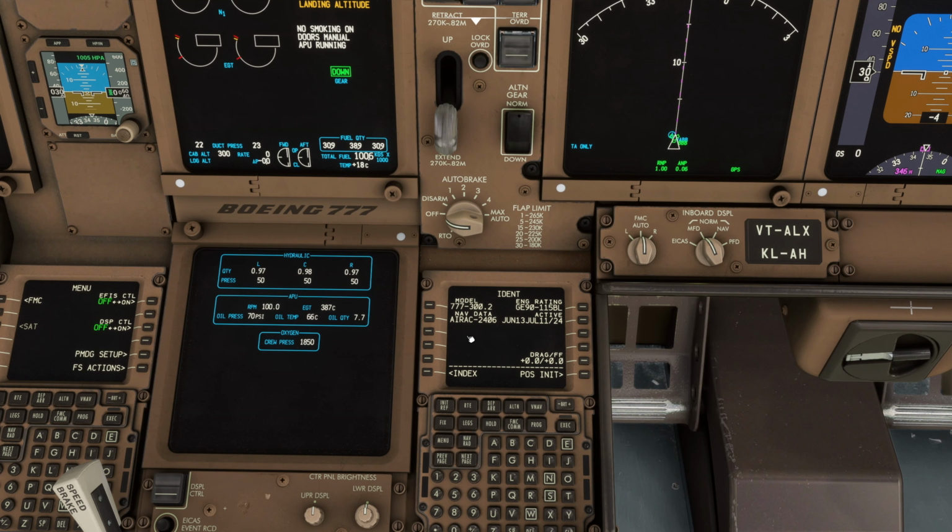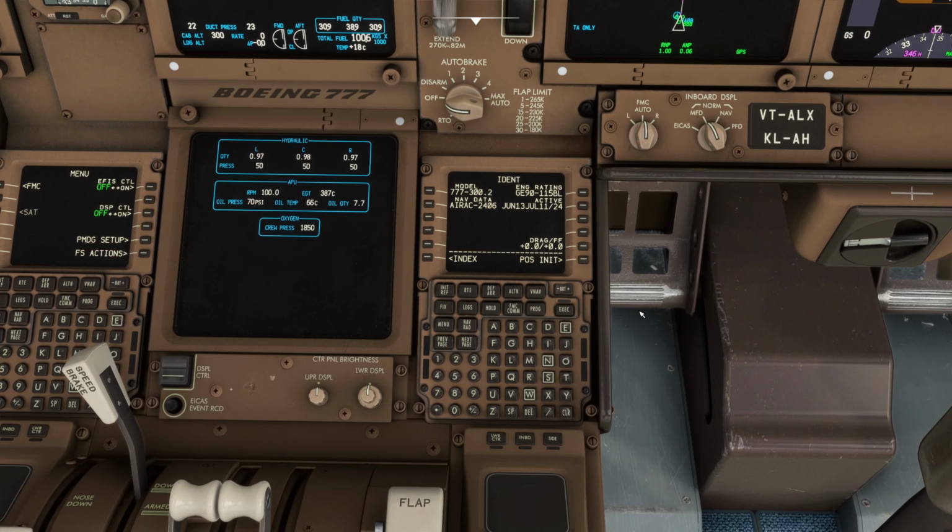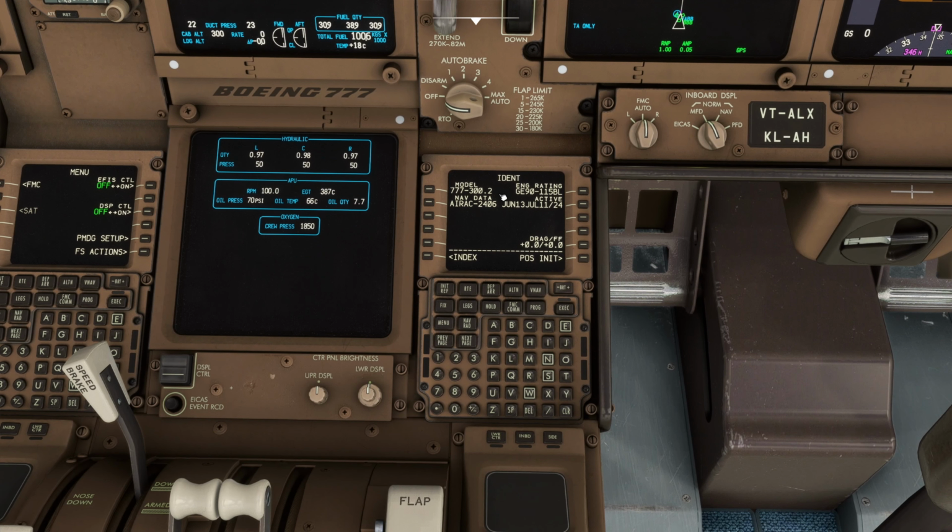So let's start with addon. The first page that you check is addon. You check the airplane model, you check the engine rating, you check the nav data should be correct. It's not correct here right now. And here from the flight plan you check your fuel performance. It should match your flight plan.